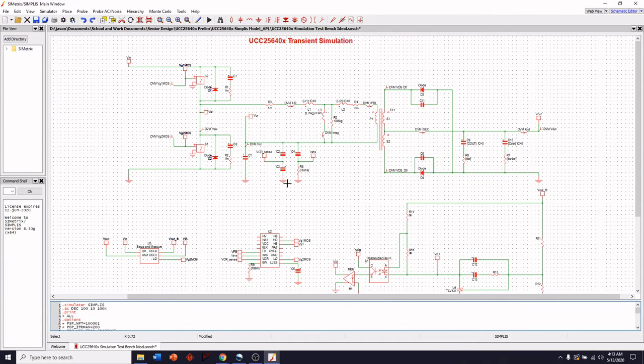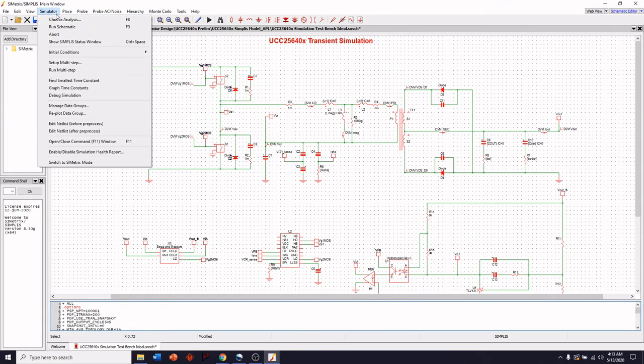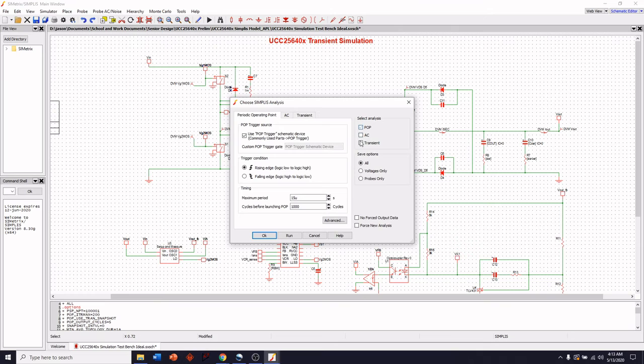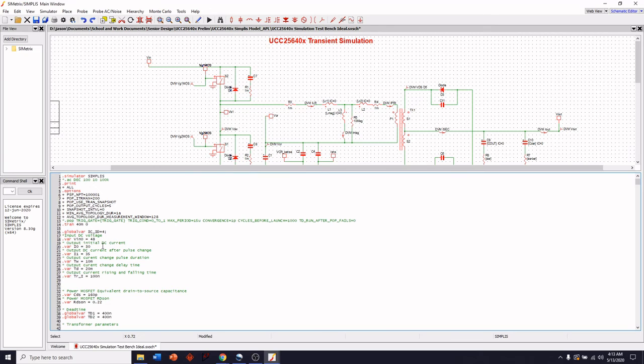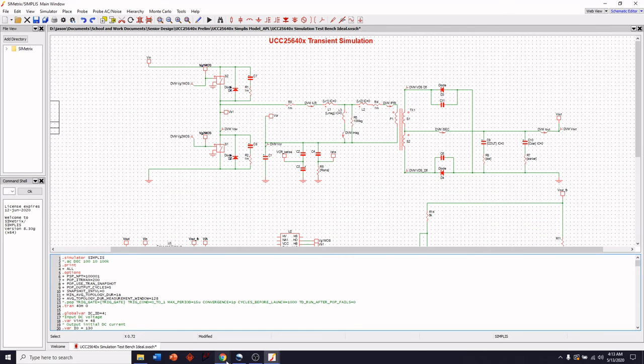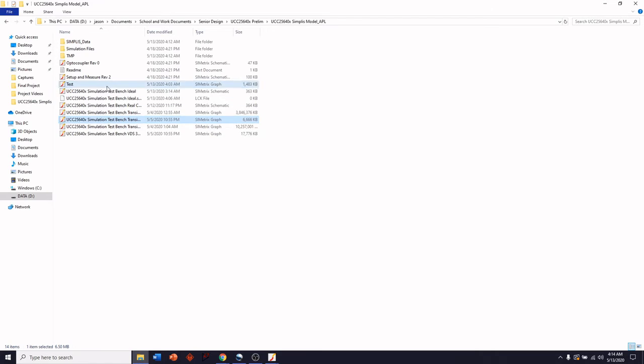And as a note, if you set the voltage or the input current, let me just change this real quick. If we go back to transient, and let's say you choose a current that's too high, you're going to notice that the output voltage never actually reaches 12 volts. In fact, it fails pretty spectacularly at a voltage much lower than it should be. Like if we set it to 100 or 130 even, and 135, I'm not going to run it right now, but what your graph is going to look like is this.